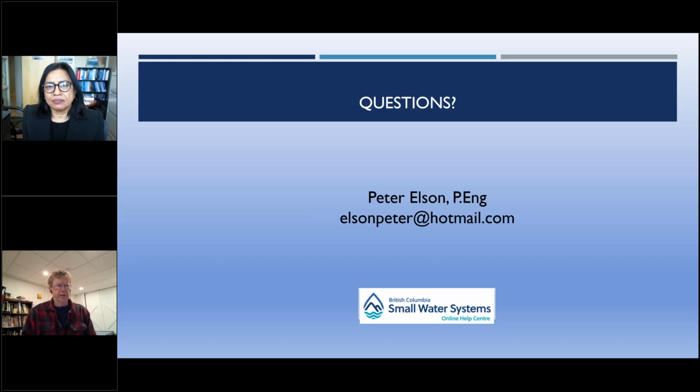And these are things you send off to a lab. I don't know how often they would want you to do the testing. I can't imagine it would be more than monthly if you're already under the limit. The limit for manganese is quite new, because really it's a cumulative effect. It's not like you get a couple of bacteria and you can get very sick. Manganese is a danger over a lifetime of accumulation of use. So if you pop over the limit once, it's not going to actually hurt anybody. So I would think monthly would probably be fine.